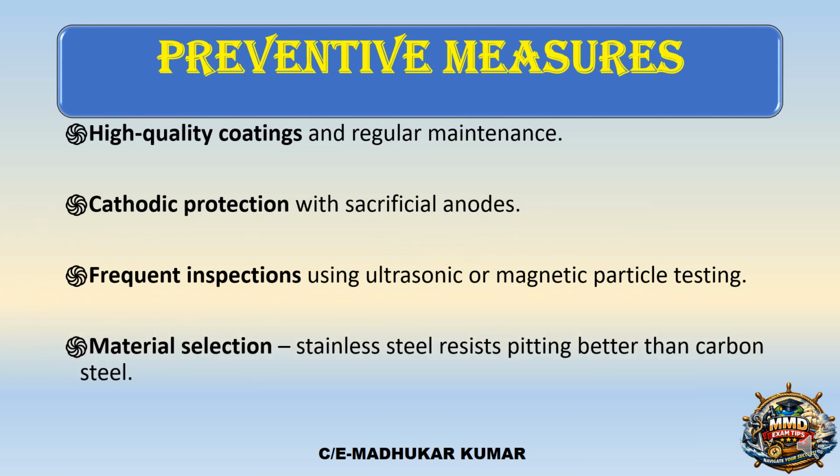Material selection: stainless steel will resist the pitting better than the carbon steel. But the commercial part also we have to see, stainless steel is very costly as compared to the MS. So wherever it is possible, it can be utilized to prevent the corrosion.